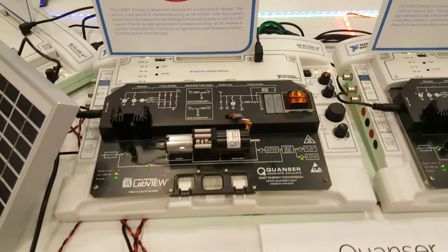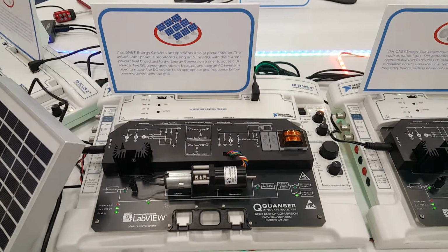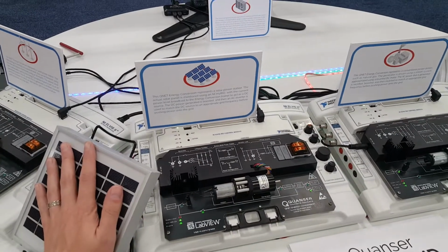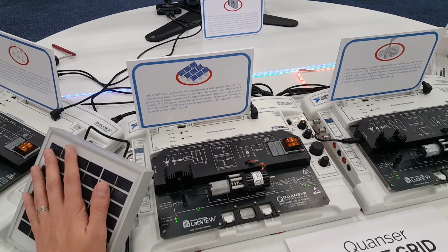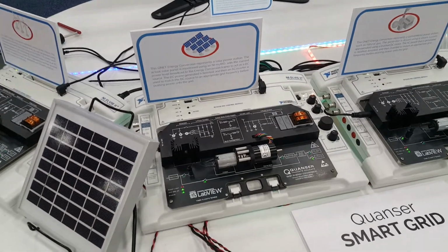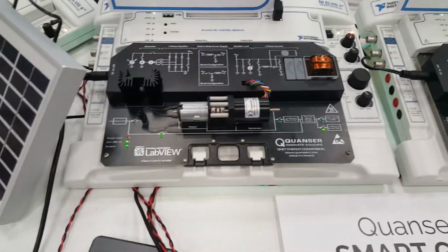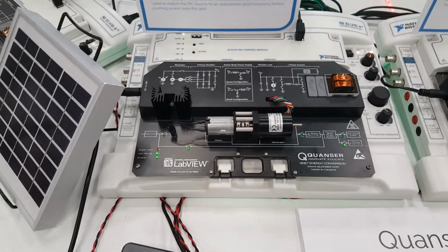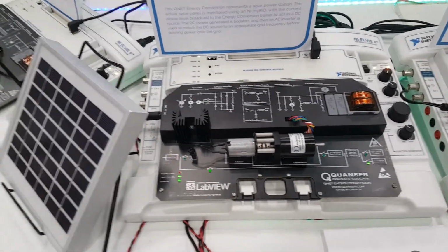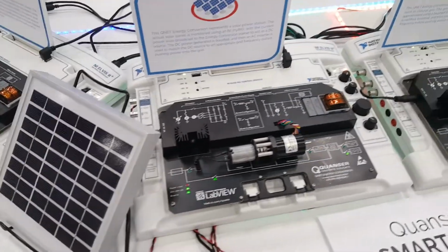We have our second energy conversion board. This one represents a solar panel. This is our solar panel here, which is being measured by the MyRio. The data on the solar energy gets sent to the energy conversion board from the MyRio through our IoT network. So that tells this board how much energy is being created. And this does that same process again, where it takes that DC power, boosts it, and then rectifies it so it can go back onto the grid. Sorry, inverts it so it can go back onto the grid at the same frequency.